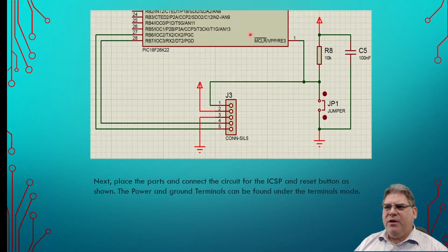So what does it mean with a not memory clear? What it means is that as long as this pin is high, so this pin has some voltage on it, the microprocessor will run. If it goes low, so for example, this jumper is closed and it's pulled low, it'll put the processor into reset. So if ever you have a microprocessor that isn't running and it's a new design, the first thing you should look at is the memory clear, is it held high, and do I have power to the chip?